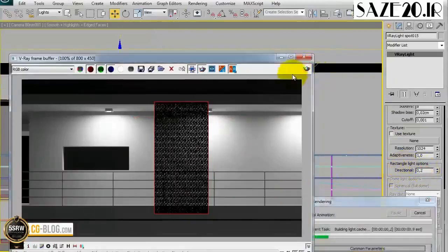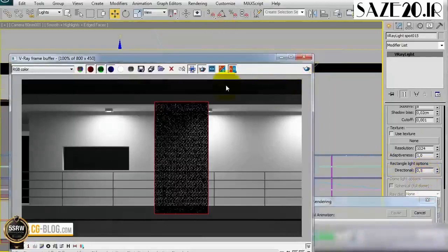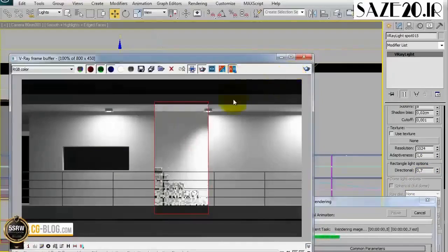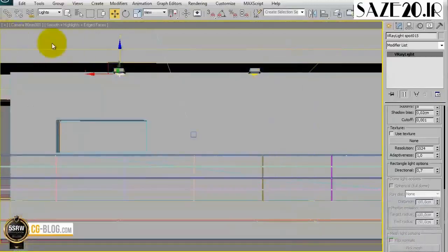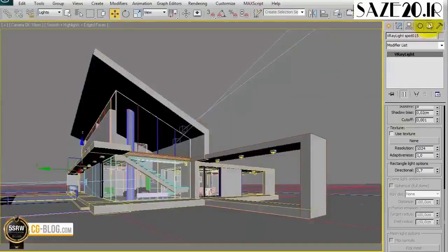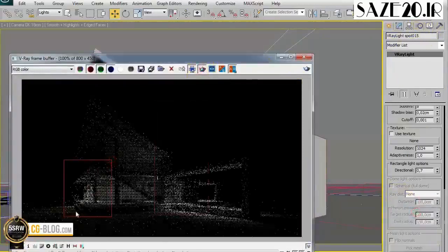0.2, 0.5 already shows a light very close to the light we intended to simulate. So we can use an IS, but we can also take advantage of the directional parameter of a common V-Ray light plane. Go to our camera view and see the final effect.